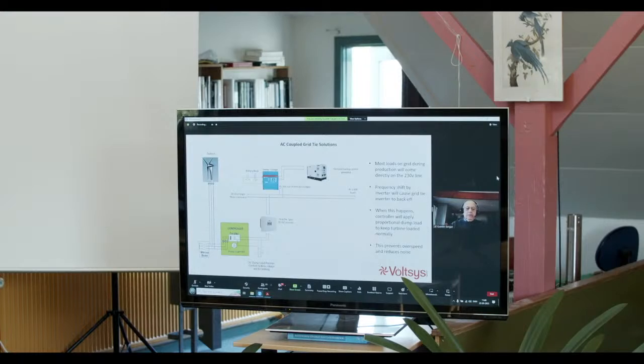For off-grid applications, rather than putting the turbine directly into the battery, in an awful lot of older off-grid applications, the turbine was put into a battery, which means that the MPPT tracking for the turbine was not observed. The turbine spun freely until it got to the battery voltage, and then it was locked to that battery voltage, working basically the same way that an asynchronous turbine would work. It was fixed to almost a fixed speed.